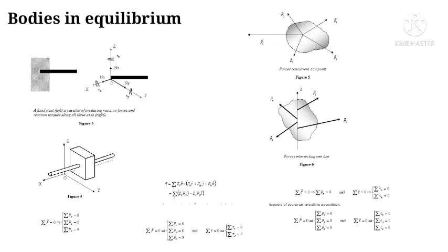Next, consider a fixed connection, say in a wall, which is capable of providing force along the three axes and also providing torque about the three axes. Thus in 3D it will be represented as shown in the figure. This is the generalization of the fixed or welded support in 2D.